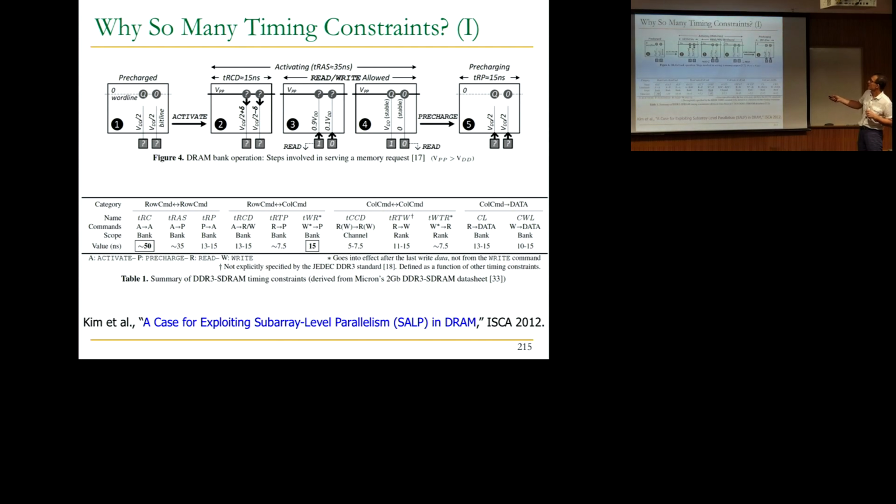And at that point, the cell is ready to be pre-charged. So the sense amplifier, once it captures the value, it's ready to be read, but it takes some more time to restore the full value into the cell. And once the cell value is restored by the sense amplifier, you can now pre-charge the array. That's why it takes more time to do that.